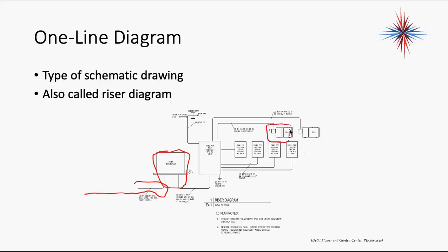There might be additional, these are my air handlers up here. And all it does is give from the panel what has to be wired. There's sub-panels here. There's 3 sub-panels. But again, it's called a riser diagram. You don't have to worry too much about these, except to make sure that all of your air handlers and equipment has wiring. They're not shown all the time on every print, but if they're there, make sure they match what you're installing.